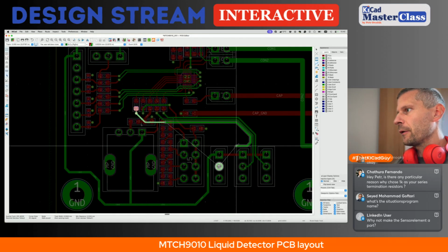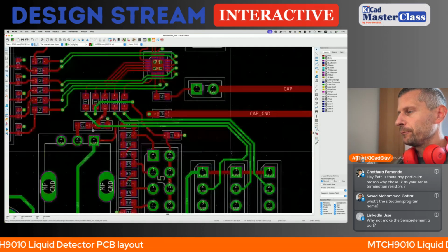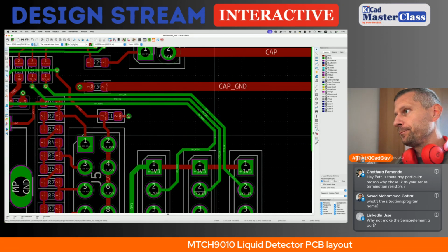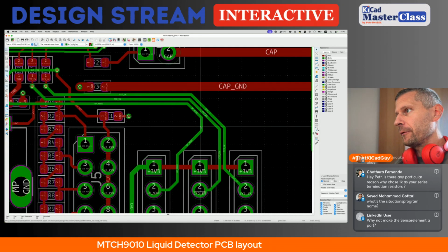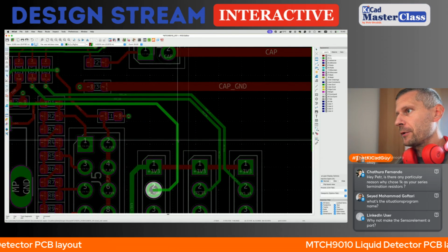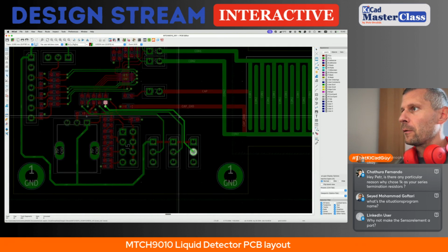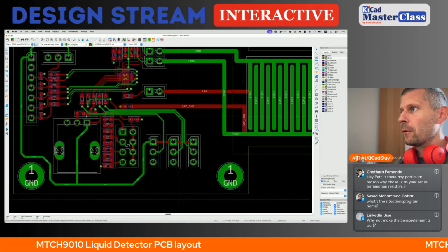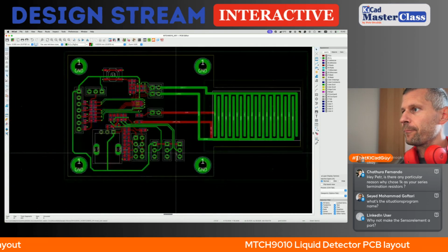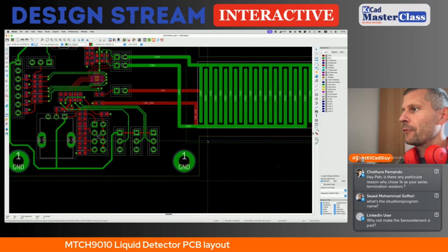I want as much copper pour on the bottom layer as possible. But this area is not so important, so I will remove it completely and route it this way. Yes, that looks good. Even better. Perfect. Okay, so I think we have the connected board.